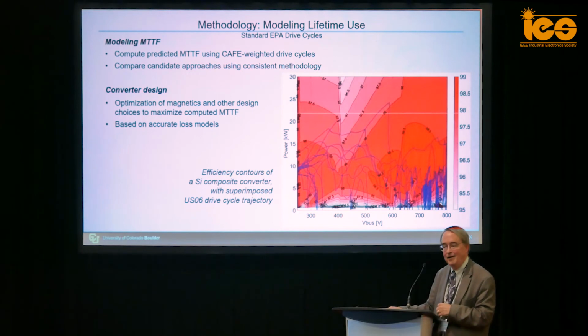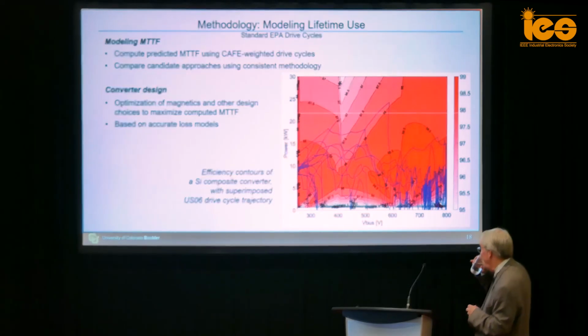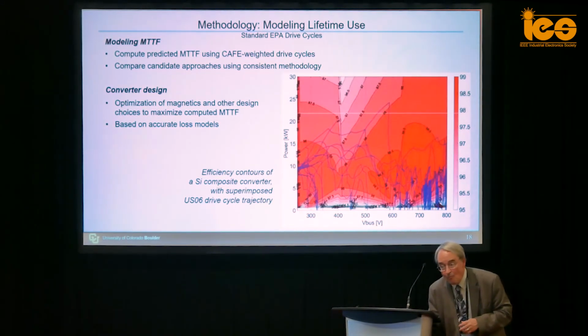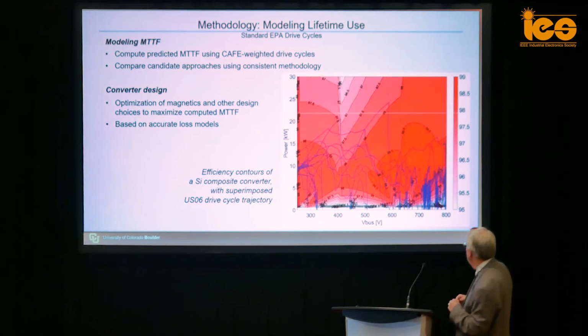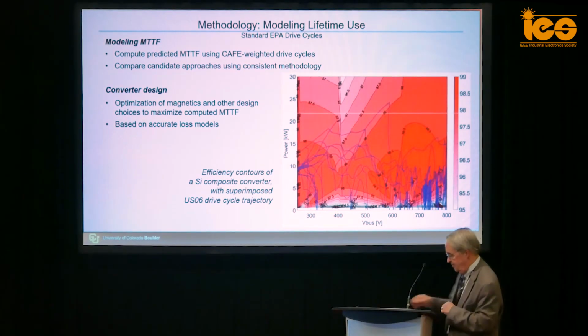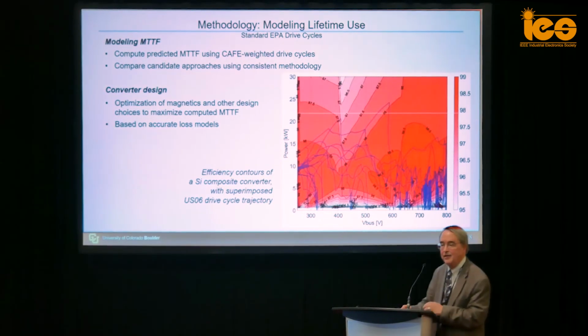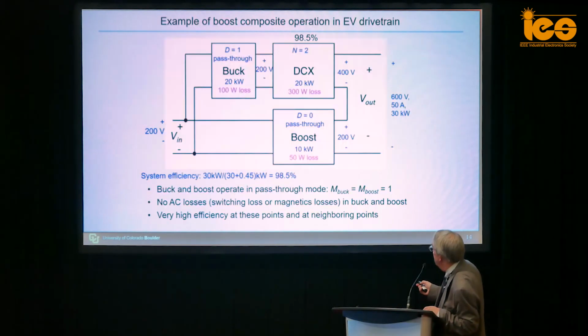He is using 400 watts of losses to push 20 kilowatts, whereas he's only using 50 watts for 10 kilowatts. So his long path is not optimized. You have 400 watt losses in the two boxes for 20 kilowatts, whereas on the boost type you have only 50 watt losses.